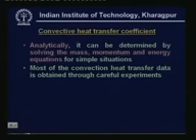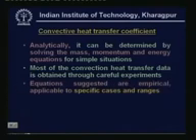That is what is mentioned here. Most of the convection heat transfer data is obtained through careful experiments, and the equations suggested are mostly empirical. Once you have empirical equations, they are valid for only the set of conditions under which these equations were derived, and they are also applicable to only that particular range of experiments. So, you must be very careful when you are using empirical correlations. You must check that your problem falls in the range of that particular correlation, only then use it.